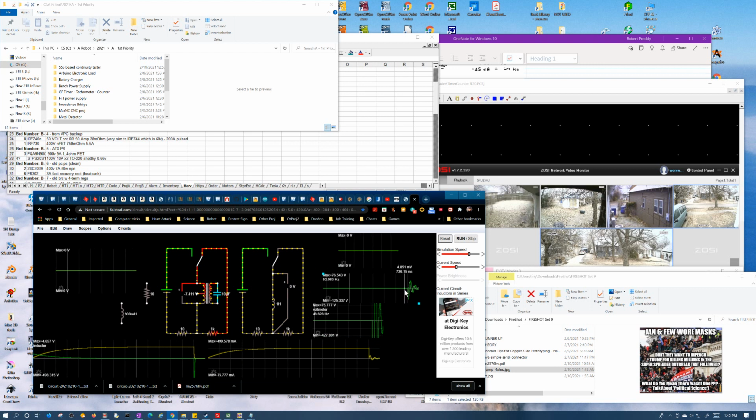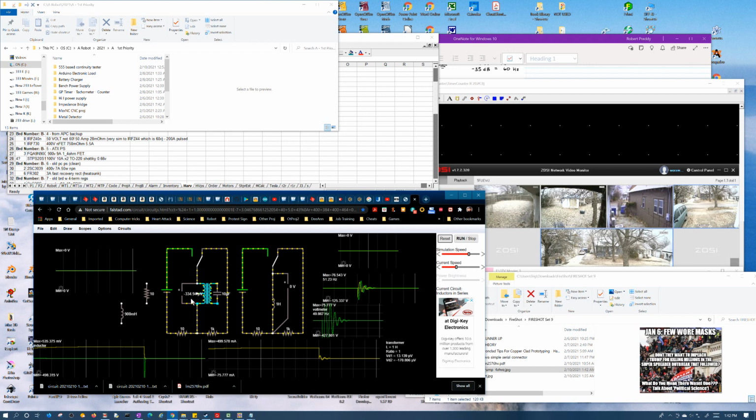Alright, so now you can see the oscillation taking place, and we're talking 76 volts versus 125 volts here, and then even here you've got 427 volts versus 75 volts. So it definitely has a huge impact on what goes on in the primary. If you had some sensitive circuit here, it would be getting whacked by some really huge voltages because of this.